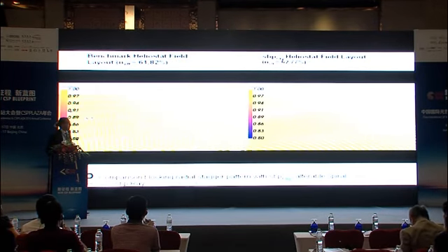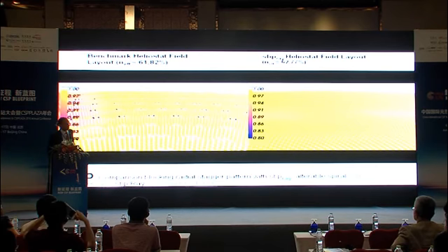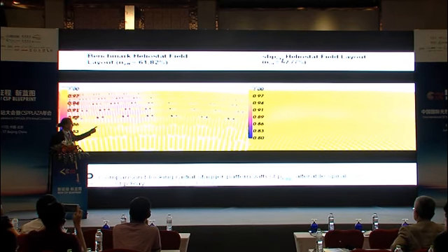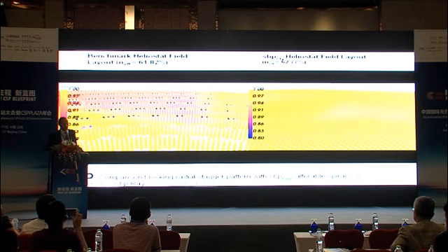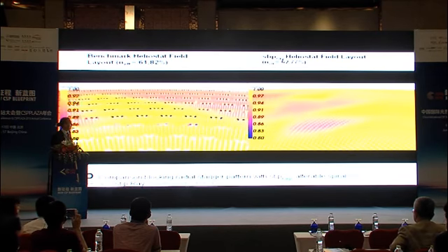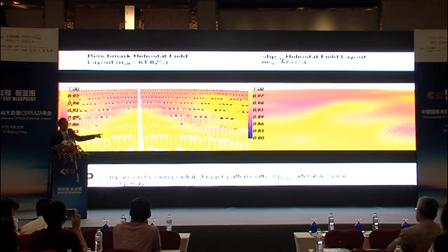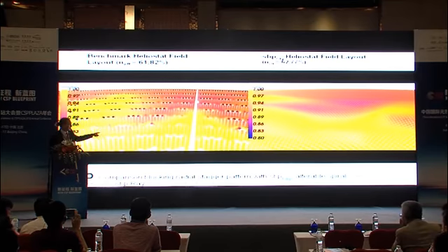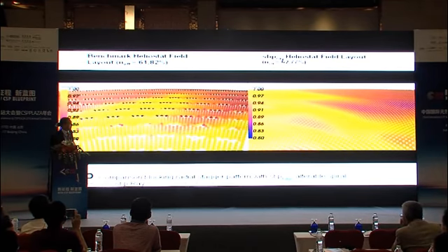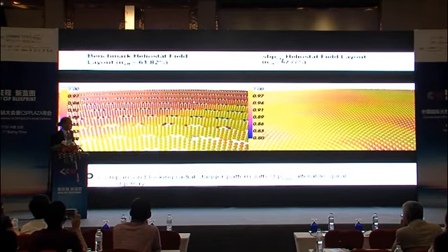So if you see now the left side one, that's the radial stagger pattern, and you see the blocking of the heliostats, and when they stand in front of each other, that's when you can see the blue ones. That means that the heliostats are blocking each other quite a lot, and they are very inefficient. In addition, looking down from the receiver, you see holes in the reflective surface, which means that you have actually losses because you could have placed your solar field much denser.